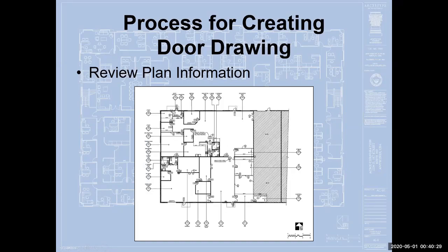The contractor can follow them in an orderly fashion, because we want to make it easy for them. And in there, we will also see a symbol that indicates the door number, the door type, and the hardware type. All three of those will tell us a whole bunch of information about that specific location.